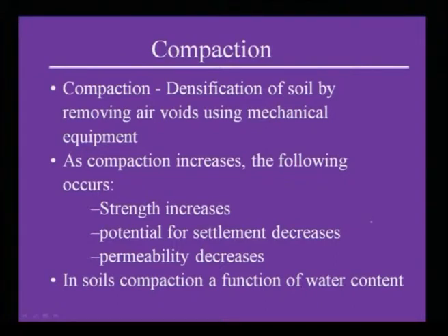So, as the compaction increases, the following occurs. First, your strength increases, second, your potential for settlement decreases, and permeability decreases. The moment you increase the compaction, the permeability decreases. In soil, compaction is a function of water content.